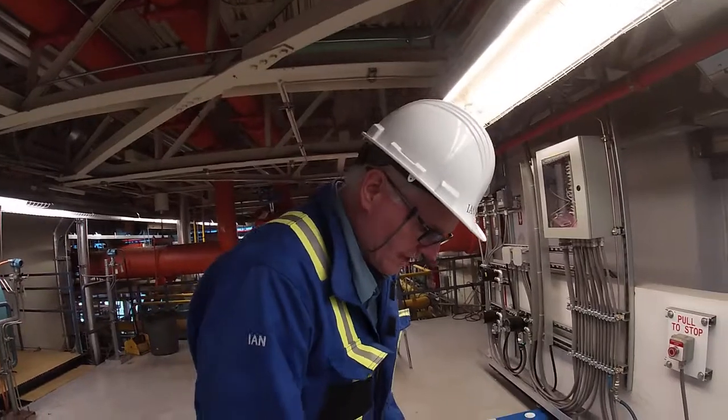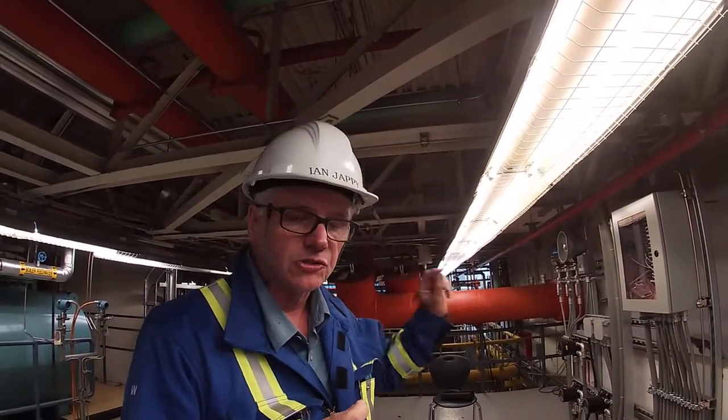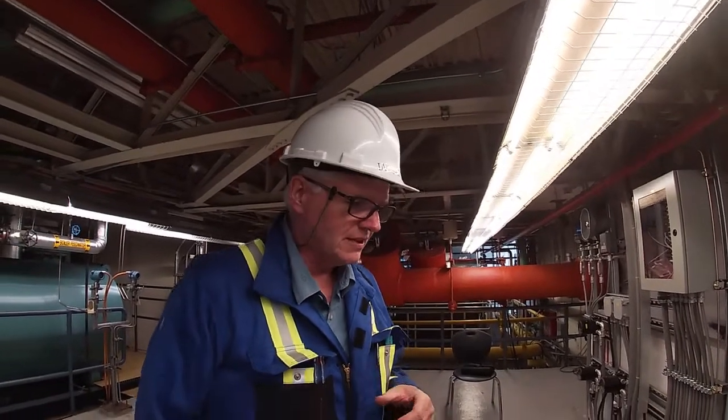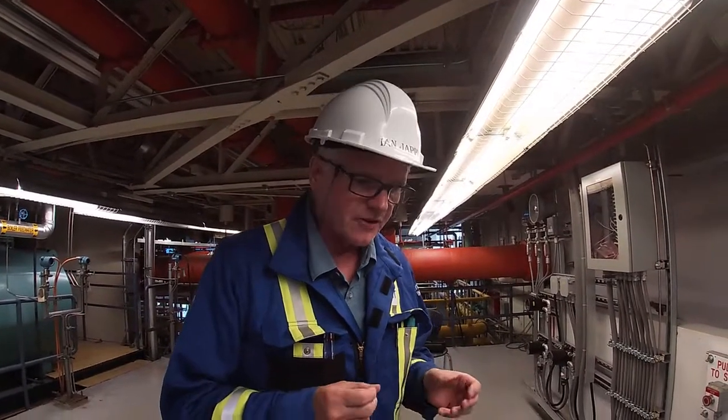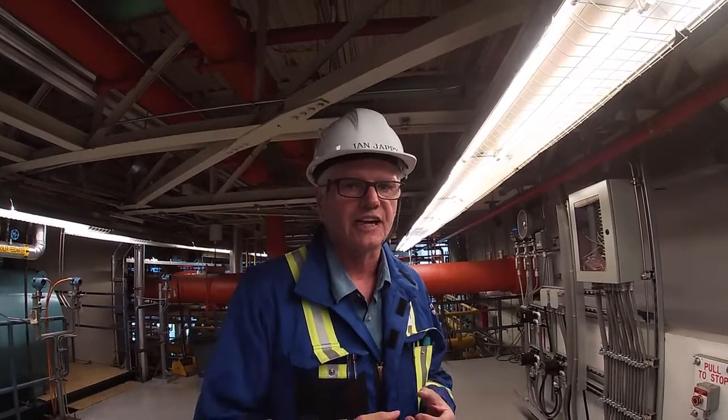So what we do with these is, if one of them picks up a flame, it'll annunciate the associated strobe, which is the white one, and the horn to let somebody know that there could be a fire in the plant. So the operations group would have to come up and do an investigation. If both of them picked up a flame, now you know there really is a fire. In other words, if only one picked it up, it could be for some unknown reason. Maybe somebody had a permit and a welding rod close by, and one of them picked it up in the line of sight, but there actually wasn't a fire.